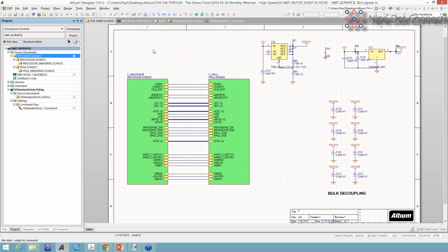So let me walk through this, and again, it's going to be kind of a quick walk, and there's probably a lot of different things that you'll be curious about, but let's take it where we can. So what I want to show you first and foremost is this: how do you put an IBIS file in? So I'm going to hit the J key. That brings up what they call the jump pop-up, okay? And I'm going to use something called jump component.